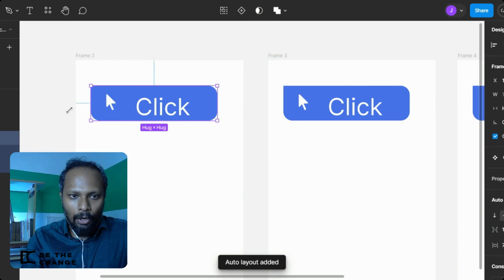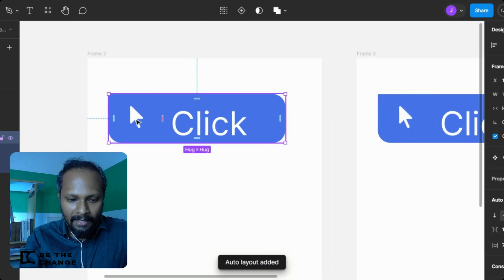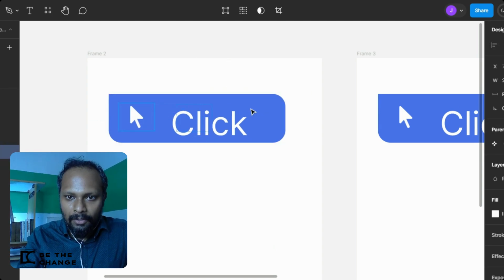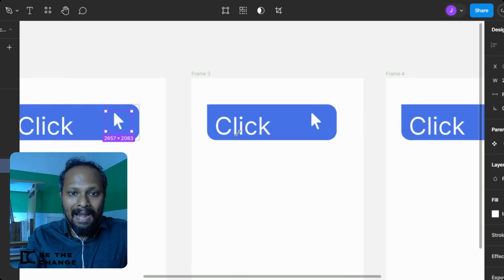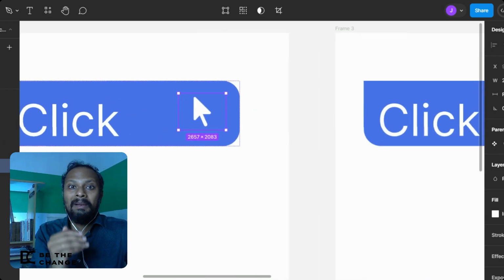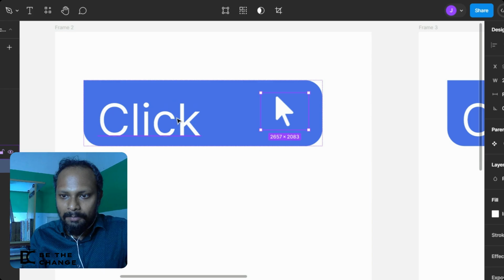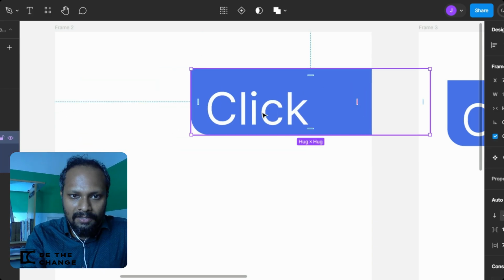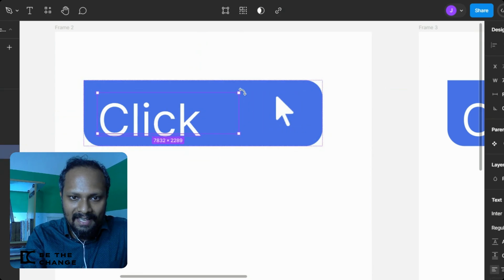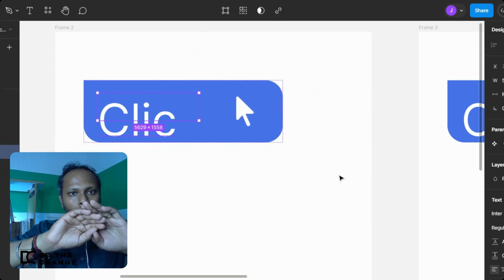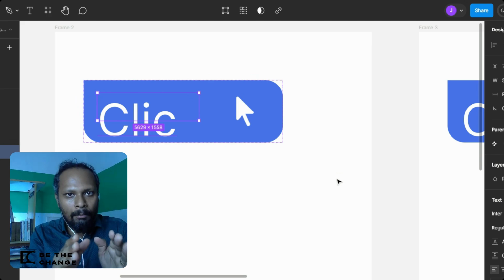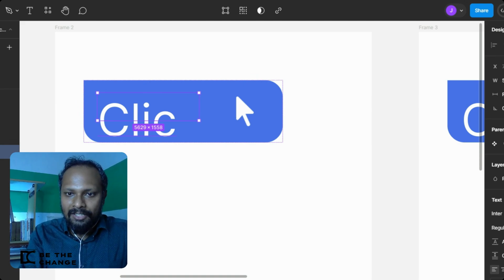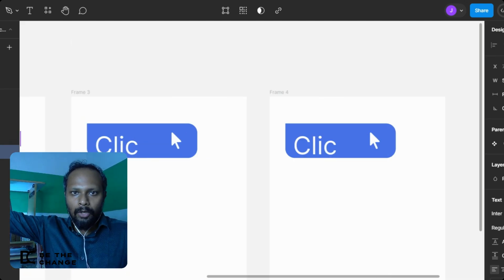Let's say if you're creating an auto layout, now you can even move this guy in a different way. Double click it and move this guy in the opposite direction. See, look how it happened. Let's say your brand guideline says, hey, all the icons should be placed on the right hand side. Hey, no, all these buttons, all this click should be coming here. Hey, no, this particular click has to come down, the size has to change. No problem, you can make any change, you can make any component movable and adjustable, you can resize everything, and it automatically gets populated in all of the 200 screens you're making.